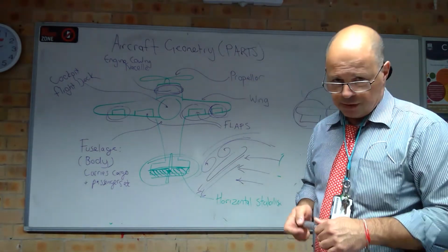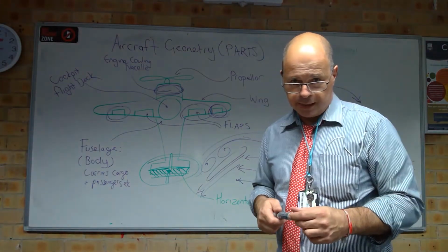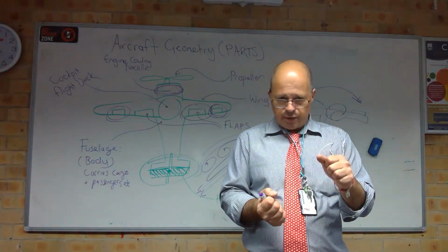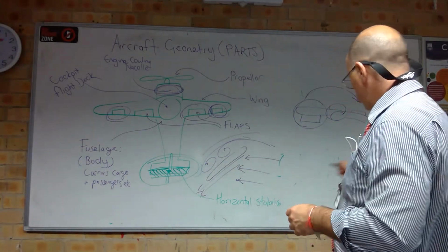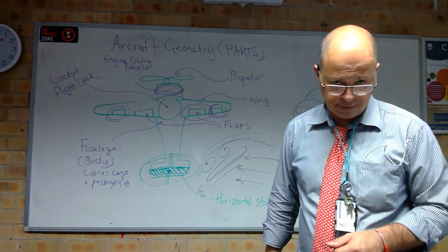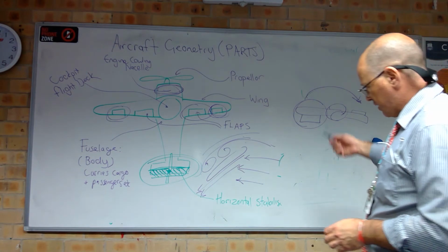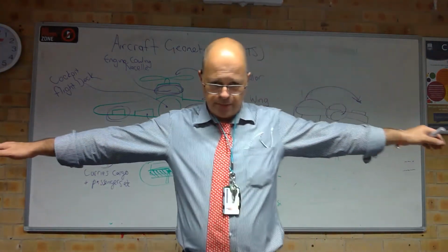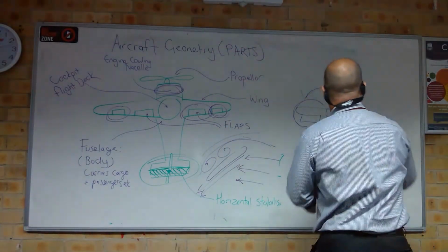Aircraft that are designed really well these days usually don't have to put too much rudder pedal in, but in the bad old days, if you wanted to keep a turn balanced, you had to roll to the right and really squash the right rudder pedal to make it happen, okay? So differential ailerons has allowed you to get rid of that adverse yaw. So that's why they're differential. Don't worry too much about that if you don't understand that adverse yaw stuff, but you do need to understand that ailerons, okay, let's do the summary now at the end of this lesson. We'll see if we can keep it to half an hour.